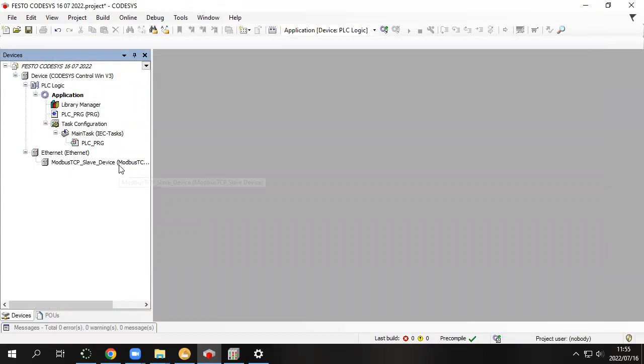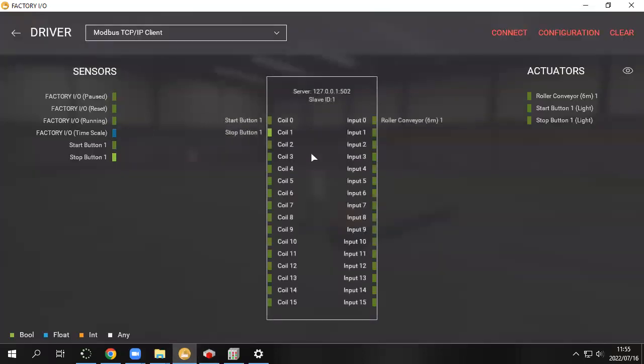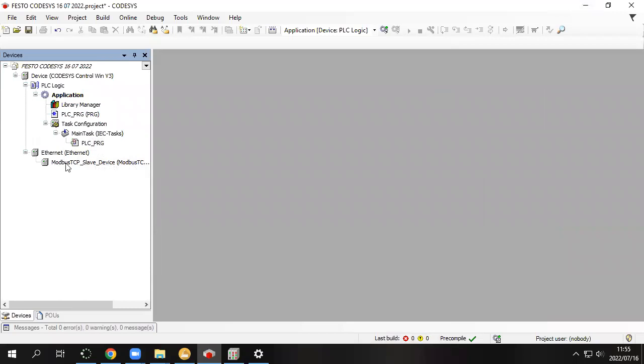We have the Modbus that corresponds with the Modbus over here. So the inputs are managed here. Input, outputs are managed here. The unfortunate part is this connection only accepts digital signals. So in future, we're gonna do analog signal, but using OPC.